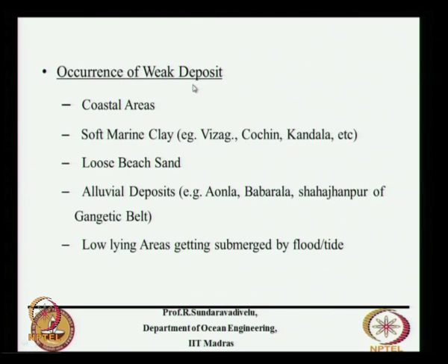So we have weak deposits. The weak deposits are in coastal areas, and one of the weak deposits is the soft marine clay. It flows like liquid. This type of deposit is there in Vizag, Cochin and Kandla. One of the structures which was built recently has collapsed because they did not take into account either improving the soil, soft marine clay, or they have not designed the structure taking the correct properties of soft marine clay.